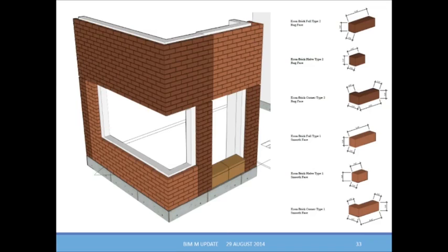It includes both three-dimensional drawings of the masonry walls and backup systems, again in SketchUp, using the bounding box models of the masonry units. Notice it's not really necessary to present the cores or the frogs or anything like that in this sort of masonry model, as well as axonometric drawings of all the masonry units used on the job. So this is actually part of many mason contractors' current workflow to draw all of this stuff, and so we should be providing them the drawings necessary.